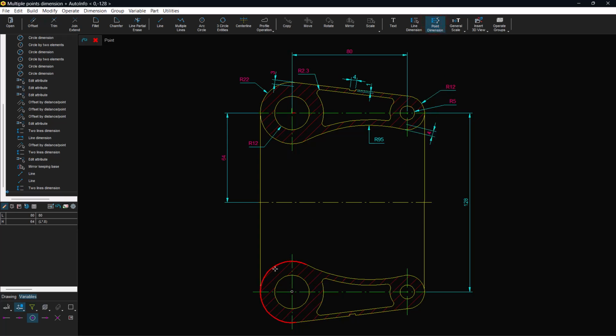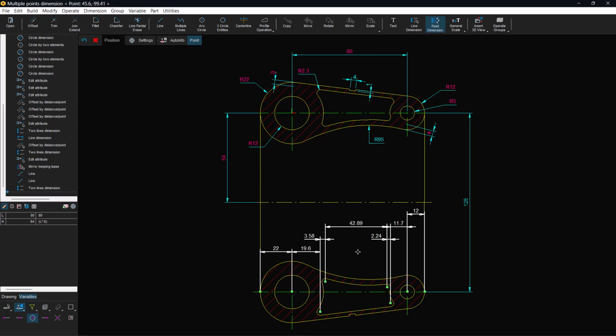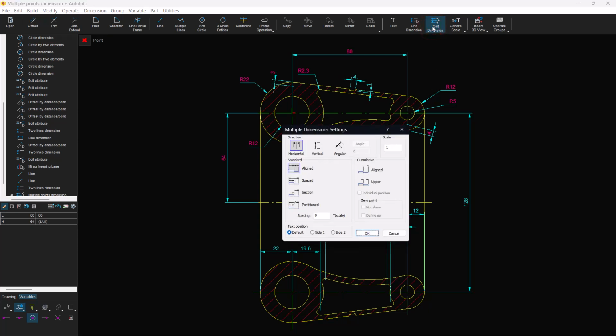For example, in the first point, we want the line endpoint. Activate the quick menu and select endpoint osnap. Pressing the Enter key, finish entering the points. There are several configuration options in the Properties box for this dimension. Test the available options.